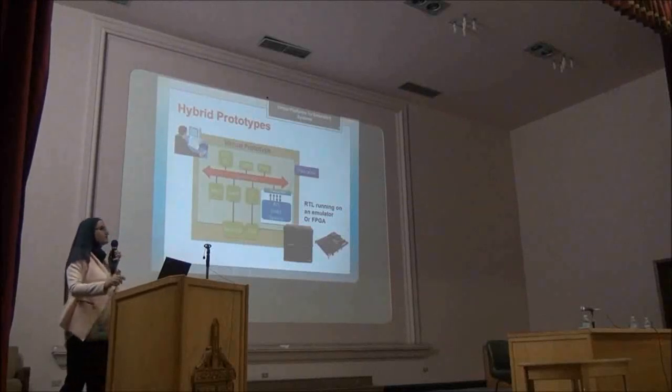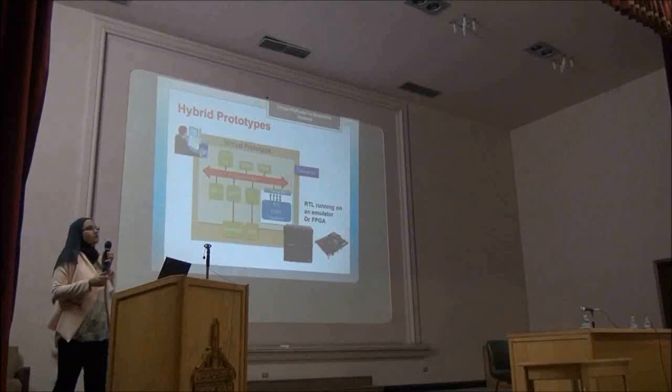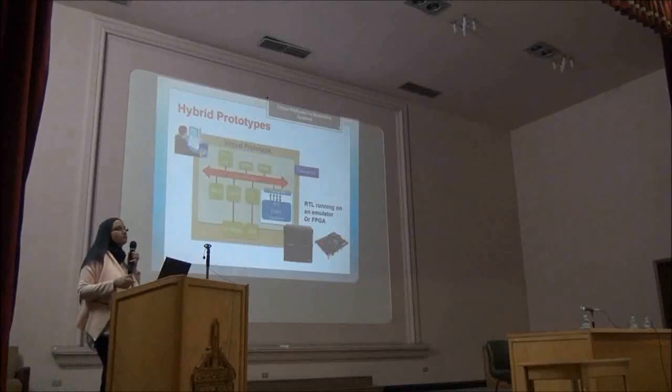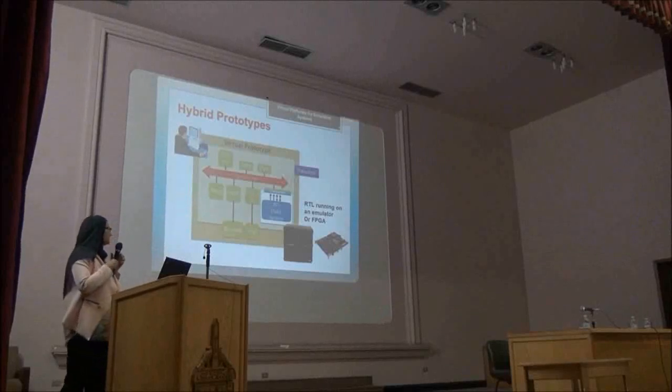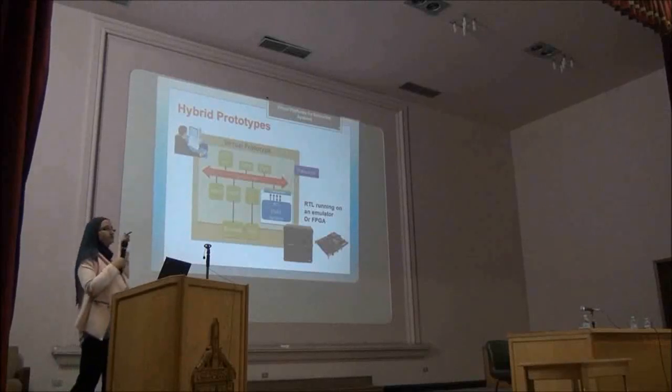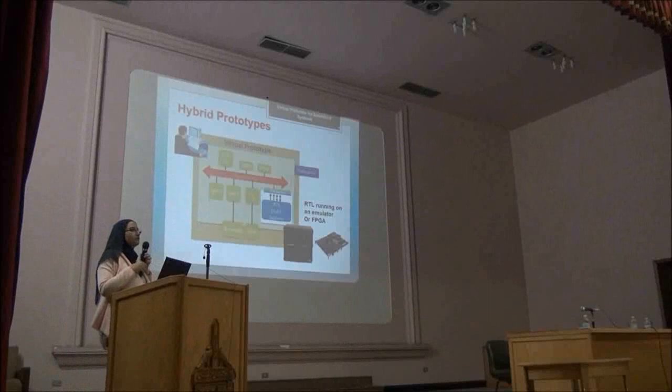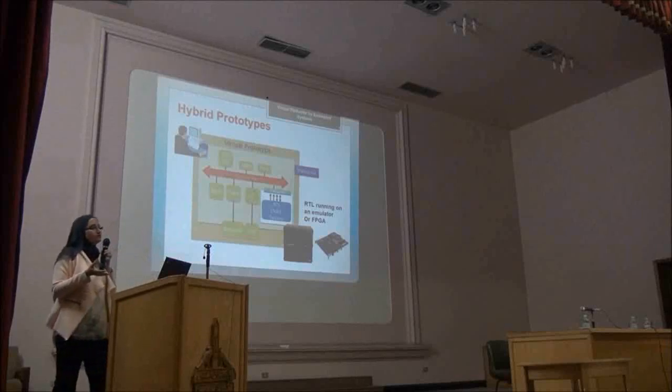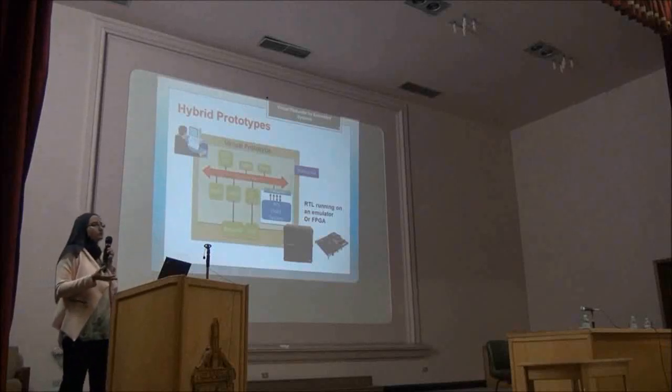What enables this methodology to work is the transaction level modeling abstraction with which the virtual platform is built, because you can rely on a transactor unit to change from TLM transactions to real RTL signals that can trigger the action on the RTL, on the FPGA, or on the emulator.